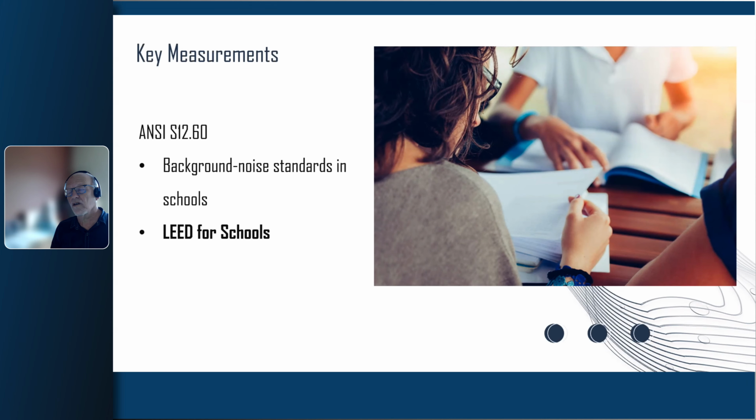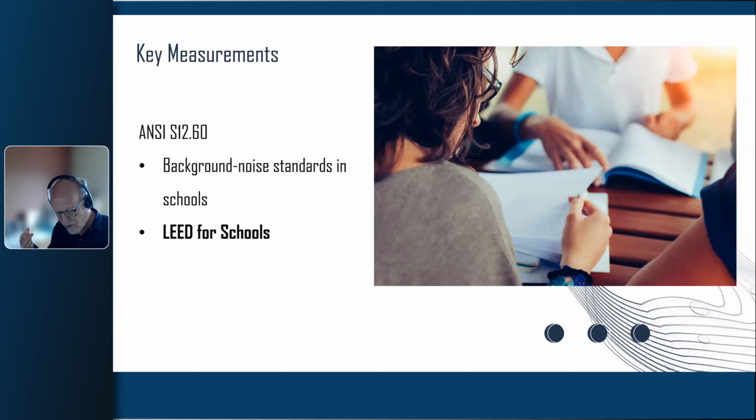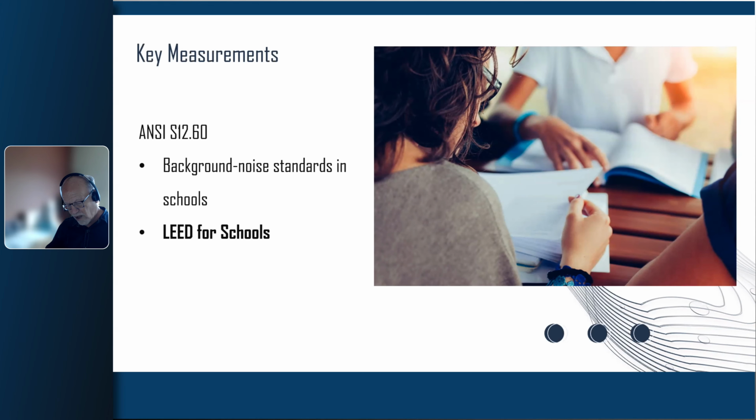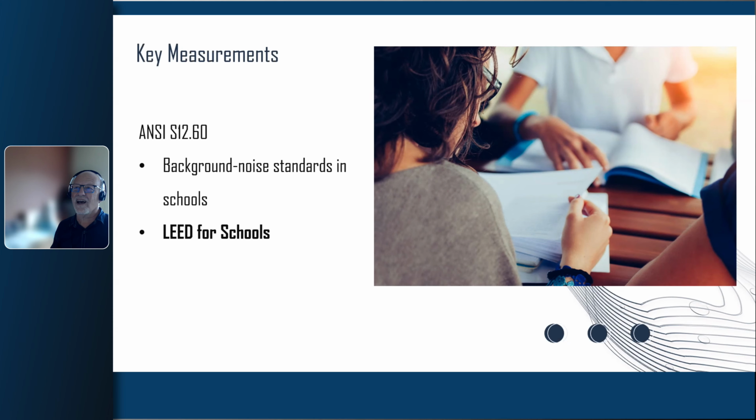The floor was far from flat. And this was in an acoustic lab with dozens of PhDs in acoustics. And they didn't bother to look. I didn't expect them to be able to design a door, but they didn't have the good sense to look and say, hey, there might be a problem here with the way this building has been built that's causing us to have a sound leak. And so that's the problem with an NIC test. That's the limitation, if you will, with an NIC test.